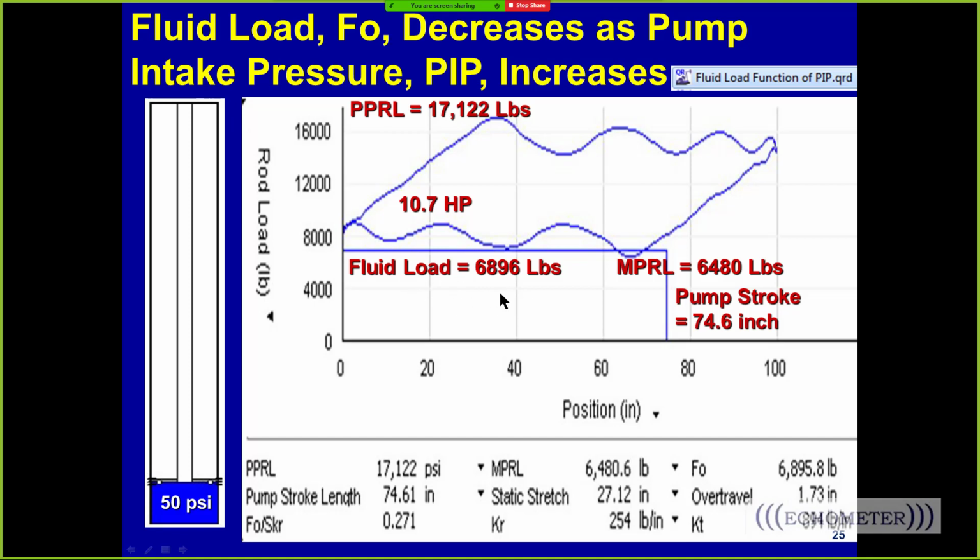And that's a good comment. We should do that and calculate pump horsepower and show that the pump horsepower is also changing, but I've just never done that before. Yes, I think as a summary, by increasing the pump intake pressure, which means probably one example is having more pump submergence, the more pump submergence you have, the more help you have from the well, and the system needs to do less effort or put in less power to lift the fluids. That's right, because the well provides more energy. But it should also show up in this area. We should see the area change as pump intake pressure changes. But that's a good answer too. I agree with what you said.